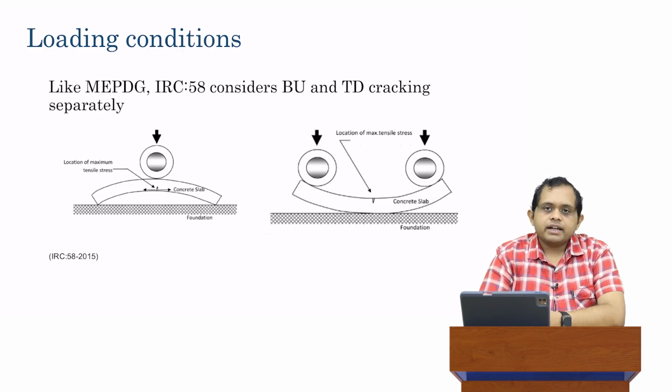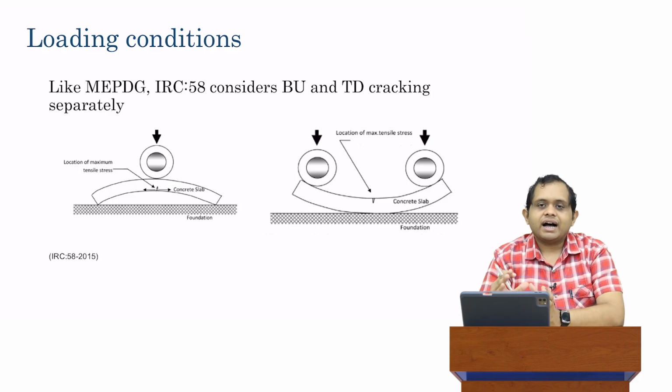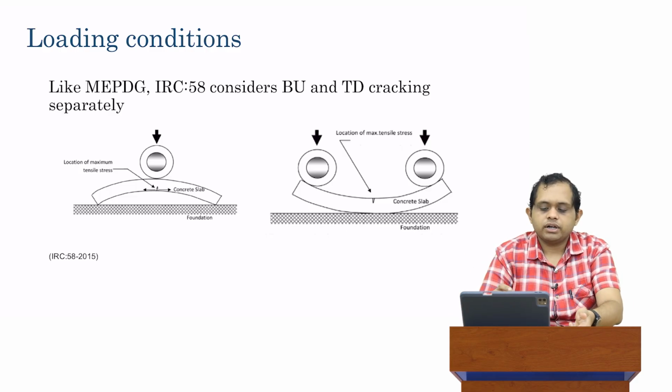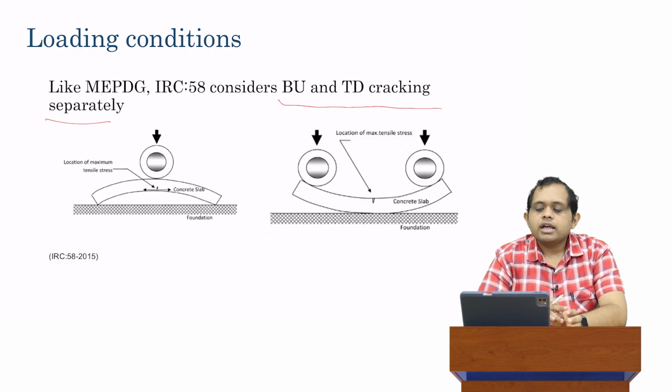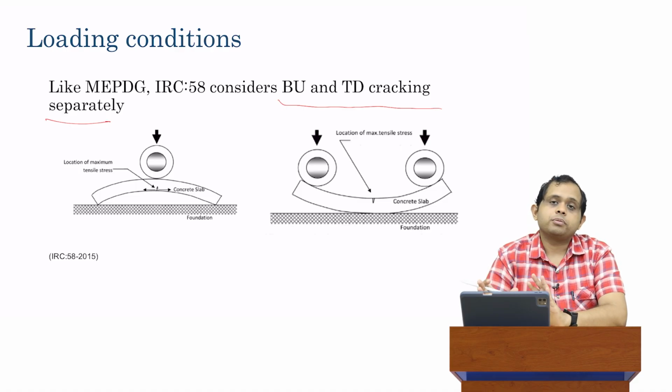Separately, IRC 58, besides talking about the critical loading conditions, I'll tell you the answer to that question in a second, also takes into account, like MEPDG, that you have separate considerations for bottom-up cracking and separate considerations for top-down cracking.